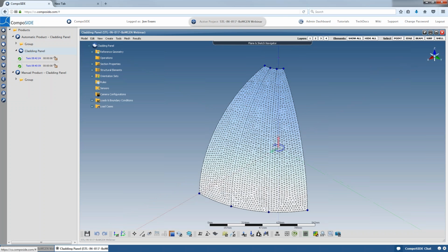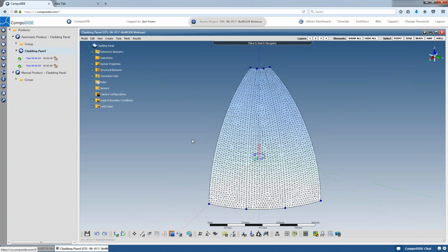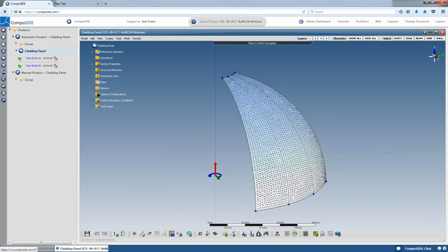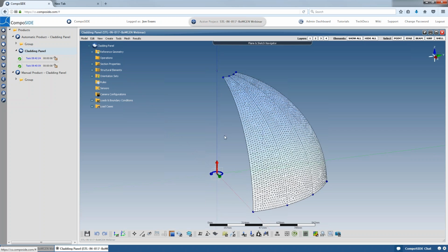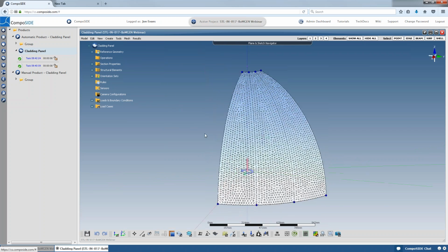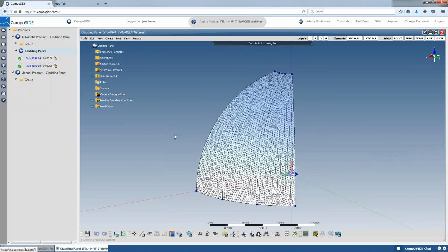Basically, by means of using the bonding, the surface element, and the reinforcement, you can basically create any composite part that exists. There is also a beam wizard that helps you to create beams in a simpler way, just specifying the shear web, the capping, and then it scales up everything and does the work for you, basically. So I think your model came up finally.